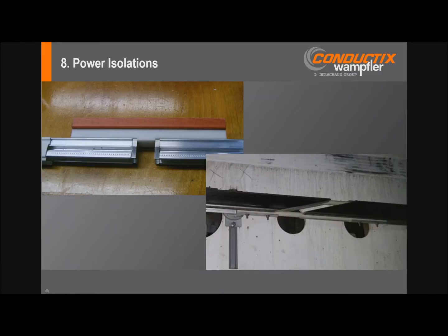Now, power isolations essentially electrically isolate the fed sections of the power rail into zones or blocks. An air gap, rather than a solid insulating section, really provides better isolation. On the left-hand side up here, on this small, about 1,000 amp conductor, we have a Delrin spacer block with a step, and then an FRP pultruded, I believe probably a channel cross-section, to provide stiffness and strength.